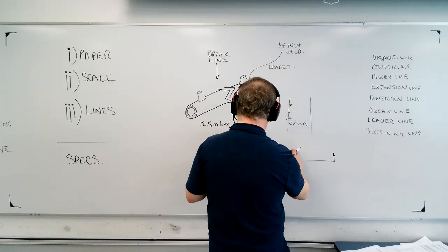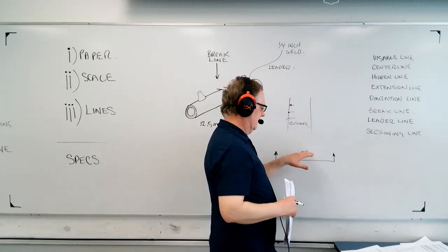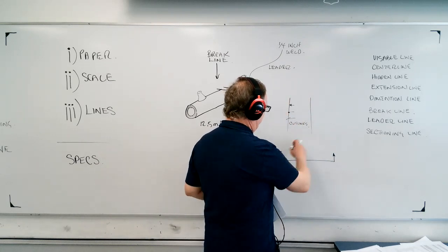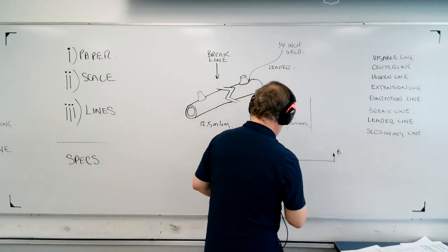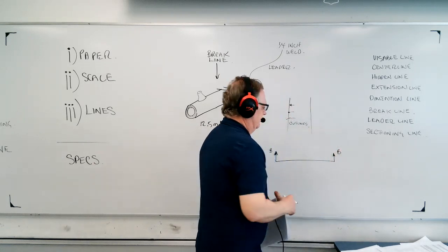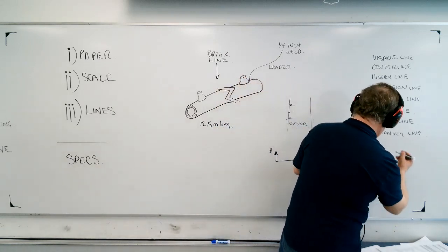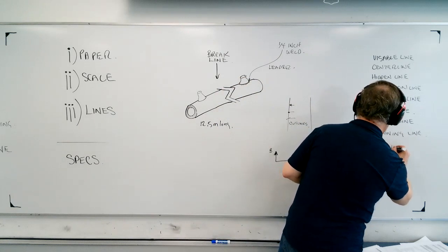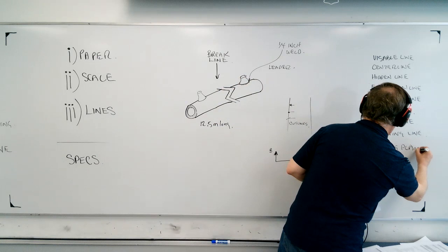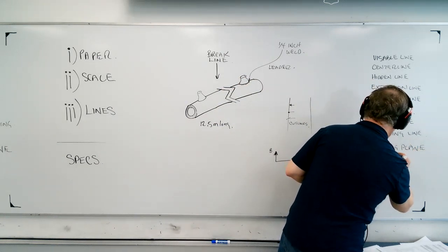So for instance, this would probably be on a floor plan, and you'd be indicating that there's a section here, and I could call this B, right? And so that type of line will indicate where the section is being cut away. Okay, so that's called a cutting plane line. Cutting plane. And I'm just going to put in brackets, that's for sectioning. Section plans.